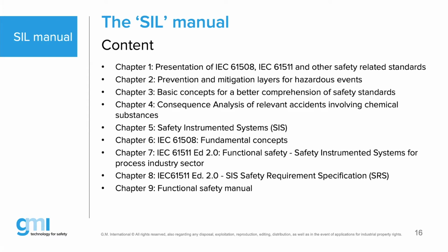And there we have given an example in the book. We're using a chemical substance which has been released, and there they will give you a few potential examples which you may recognize from your own industry or your own application. Chapter number 5 highlights the definition of a safety instrumented system, which is a combination of inputs with logic solvers in the middle and final elements, mainly an on-off valve or maybe some MCC motor starting or stopping a motor. Chapter 6 is IEC 61508 edition 2, where the fundamental concepts and the framework will be explained.